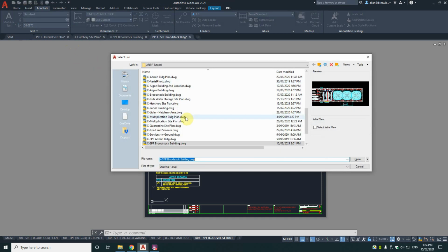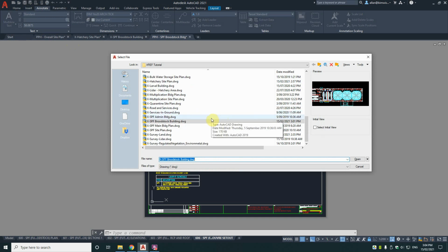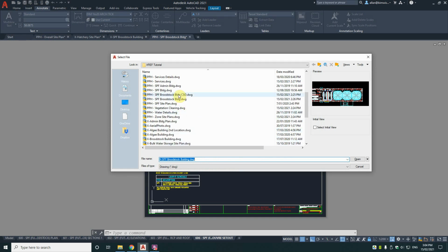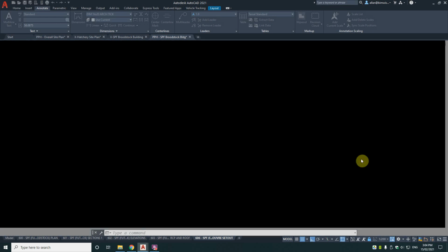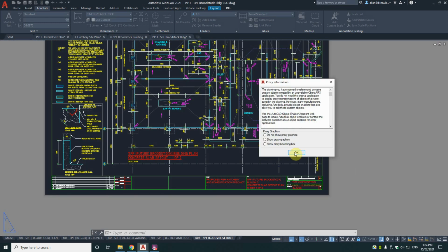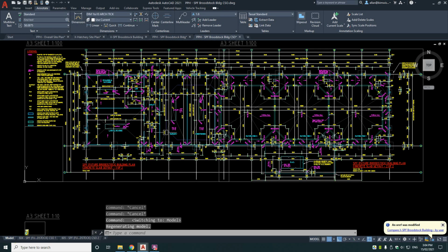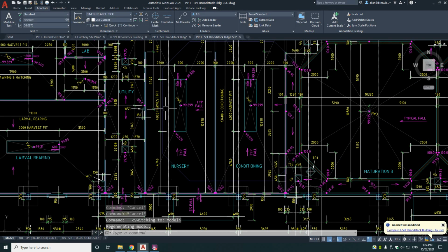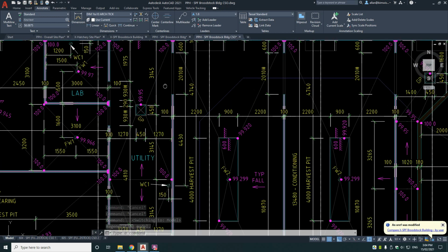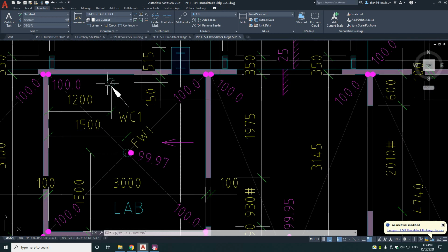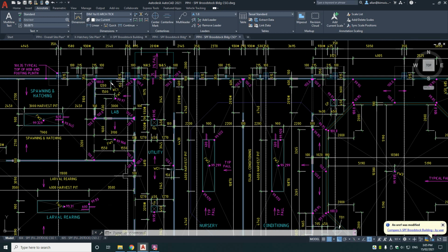Now I had to do some concrete setouts as well. So let's have a look at that, and I put that in a separate drawing. So this is where good layering is important, because in the Xrefs here of the concrete setout plan, there were some things we turned off. Like, for example, the kitchen, the plumbing. There's only the hole in the concrete. We only want to see the concrete here.